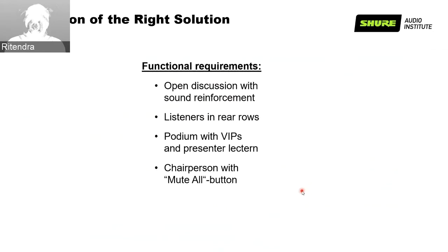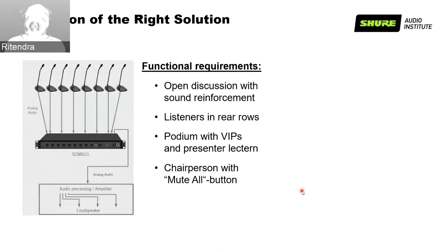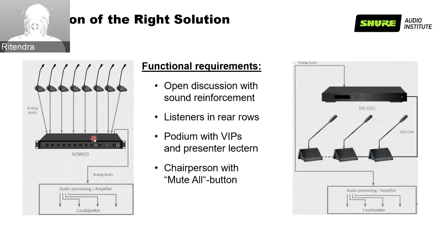In this kind of scenario, you can offer our standard point-to-point microphone solution, which is our standard desktop-based microphone, connected straight to the mixer, and you can use the control system to control the microphones. So it is very straightforward, but you can also do this with our conferencing solution, DDS 5900, where the benefit of this system is daisy chain. So you're not running individual cables.